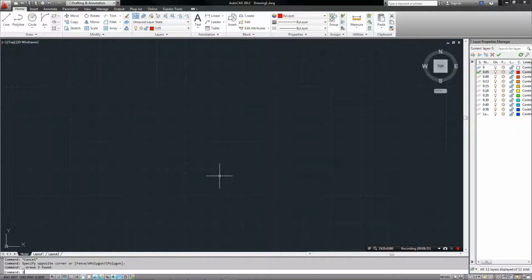Now we got the Trim tool. Got some lines. And I want to get rid of all the lines that are intersected by this line, so now I'm going to use the Trim tool. This is the line that I want to do the cutting, so I press TR, and then I can just select these guys and get rid of them, and they're all nice and trimmed. Same again, I want this to be a nice corner, so I trim that off there. Beautiful.